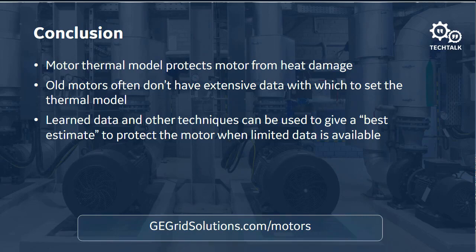If that's the case, then if I want to be very conservative, I would set the relay at 1.0 for my overload factor. Now the problem with that is it doesn't allow me to fully load the motor without exceeding the thermal capacity or starting to accumulate thermal capacity used.